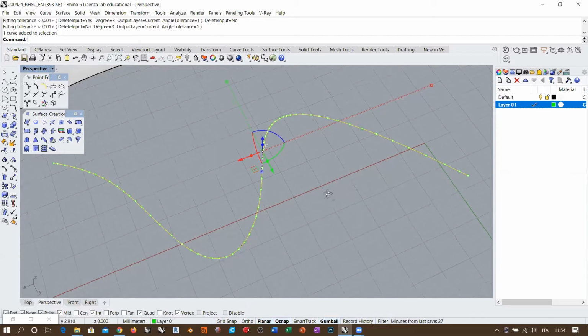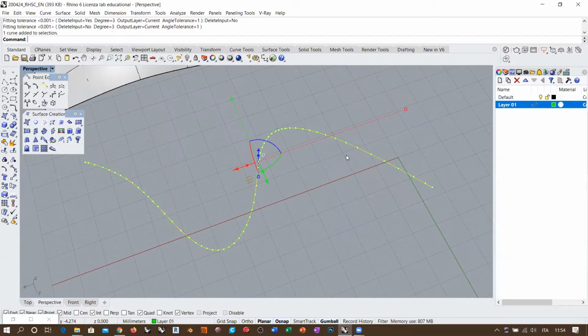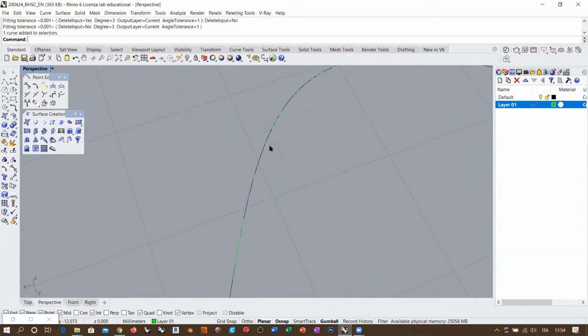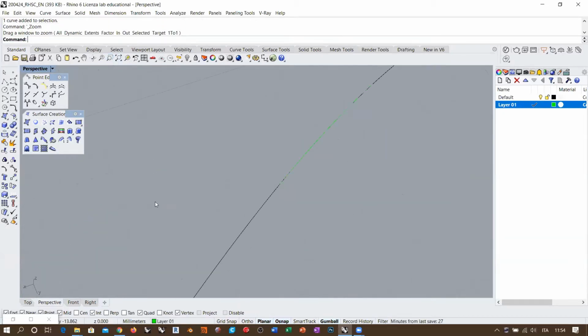So I know that topologically speaking, this might be the best compromise between the original weird topology and the best topology that allows us to respect the absolute tolerance of our document. So for Rhino, there is absolutely no difference between the green curve and the black curve. Even if we go very, very close to this line, you see that this flickering means that the curves are somehow different. So let's see if I zoom window, for example, in these areas.